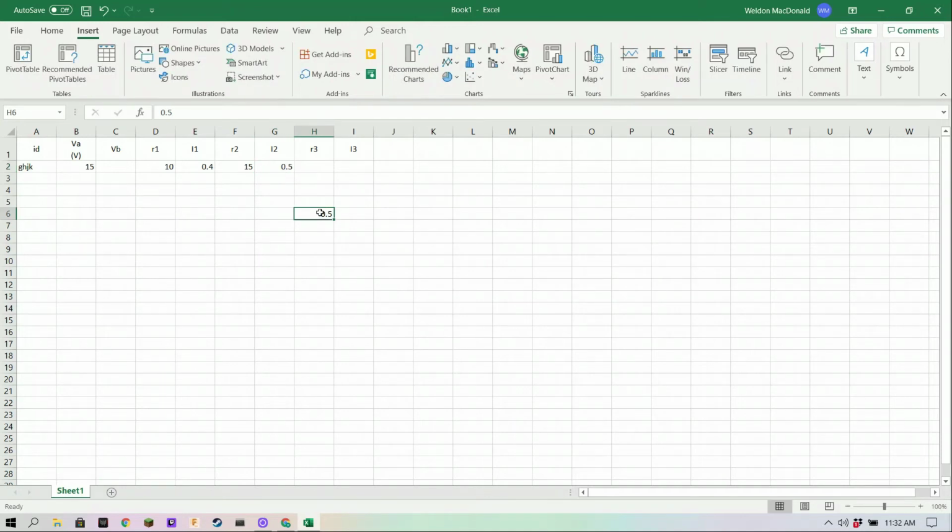Now, there's something you have to realize with the currents. When you label the currents, you're going to have to pick a direction. And if that direction requires it, you may have to put in a negative sign here. The worst that can happen if you pick wrong is that you'll end up with a negative sign, or it may not even matter. But just be aware that it may happen. And R3 is not in this equation that I'm doing, so there we go.